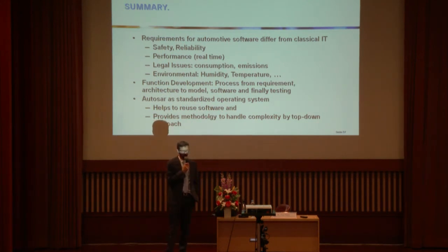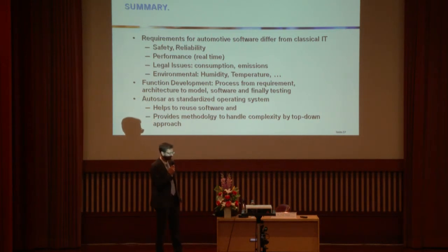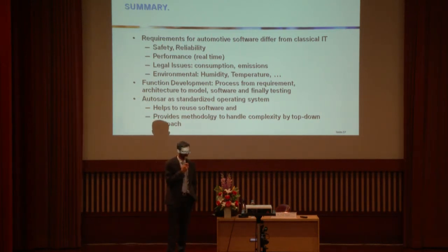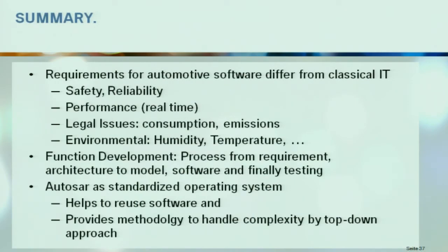From the function development, we have seen the process from requirement via architecture to the model and software, and finally you have to test the software. And as the last point, we have seen AUTOSAR as a standardized operating system, which helps to reuse the software and provides a methodology to handle the complexity by using a top-down approach, from a collection of software components down to a mapped control unit system of the technical architecture.